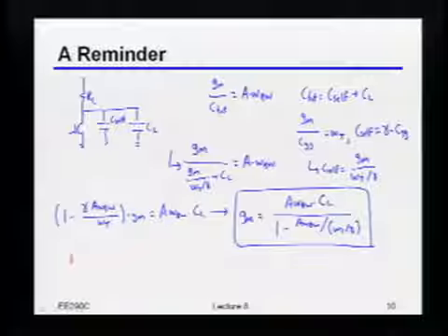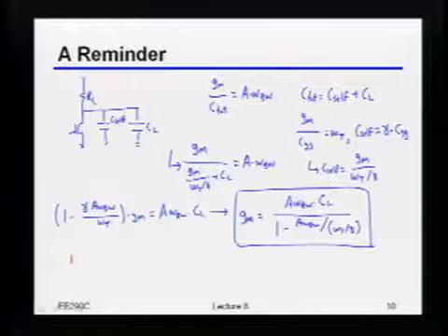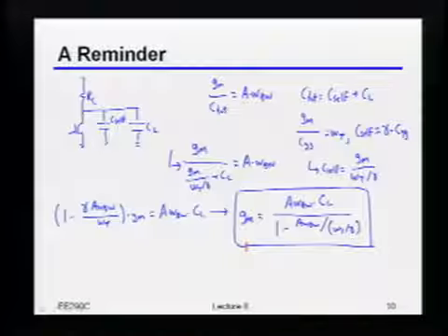So why did I spend this much time deriving this thing? Well, it gives you some nice intuition for how things behave in terms of how much power it takes you to get a certain bandwidth. Or really a certain gain bandwidth. Because notice what this is really telling you is that this gain bandwidth on the bottom is getting normalized by the intrinsic gain bandwidth of the device, right? And in particular, notice that when A omega bandwidth is equal to omega t over gamma, meaning that this whole term here is 1, well, 1 minus 1 is 0, and 1 over 0 means it's infinite, right? Forget it, not going to happen.